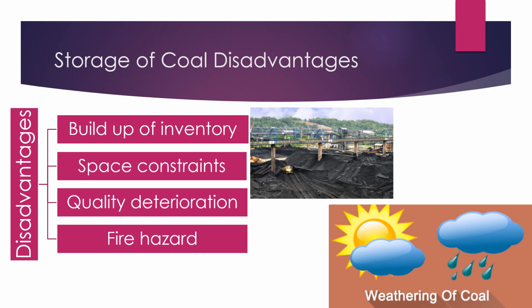Coal may catch fire when stored in a storage yard. All coals, when exposed to air, undergo natural oxidation of carbon, forming carbon monoxide or carbon dioxide and producing heat. Once there is enough heat, spontaneous combustion occurs. This gives rise to a fire hazard in the coal storage yard.